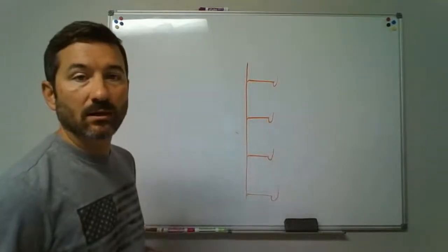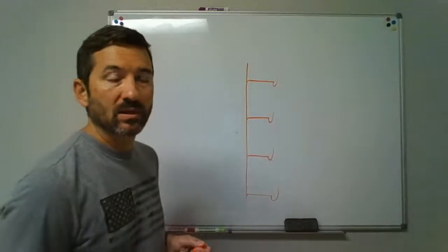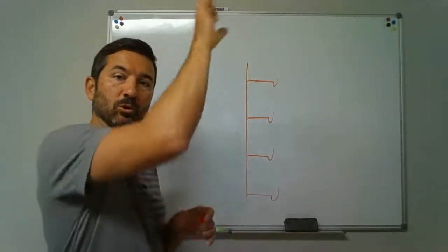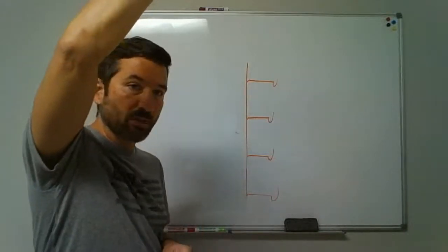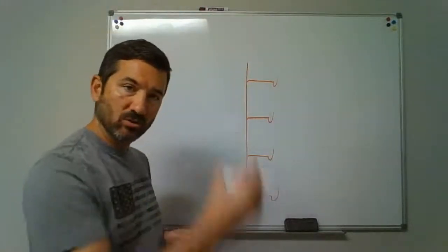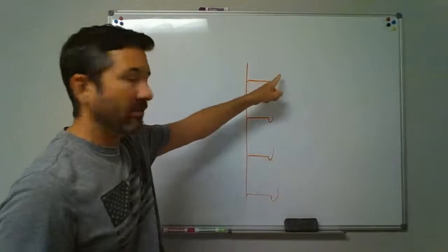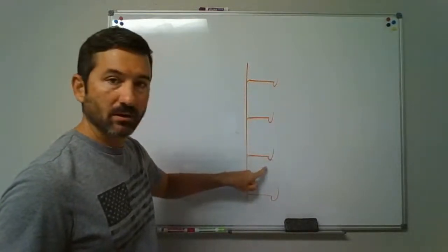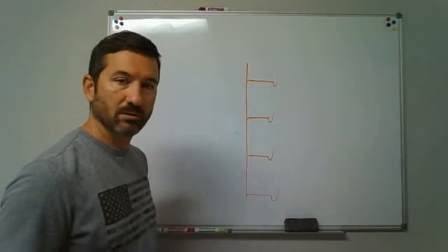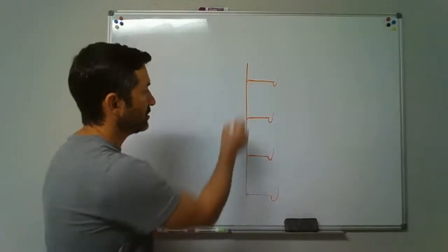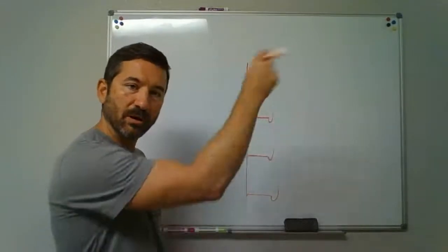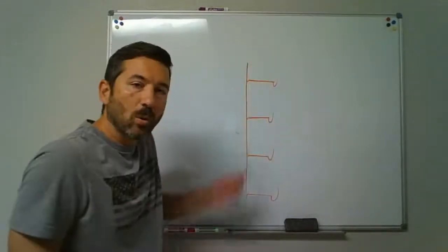You might be in a hotel, plumbing that up, and basically they've got room, and they're all straight above each other. And so that wall that's got a bathroom sink up here, directly below it, another bathroom sink. Directly below it, another bathroom sink. Directly below it, another sink. It says that you can say, well, let's just take one stack going on up and just pop out for those sinks. Let's call it a waste stack.